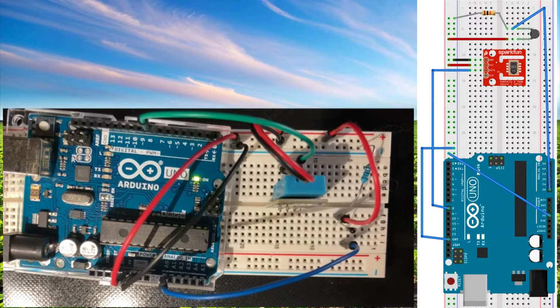Our team decided to use two temperature sensors in order to compare them. The first sensor is the DHT11 temperature and humidity sensor hooked up to the power, ground, and to digital port 8 on our Uno. The DHT11 sensor is actually a microcontroller combined with a thermistor and humidity sensor. Because of this, we can interface with the controller digitally instead of analog.